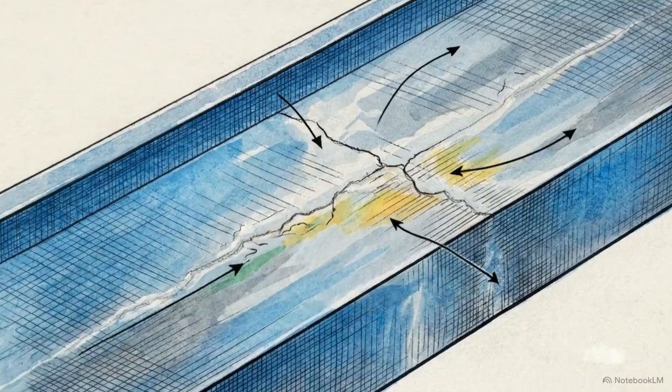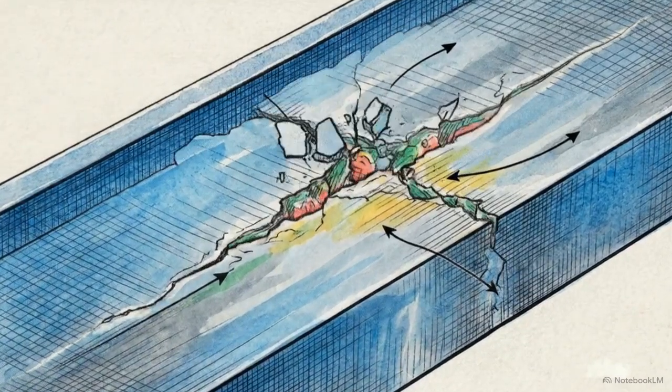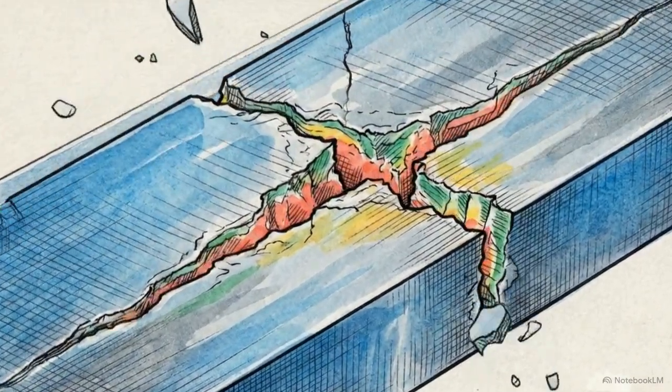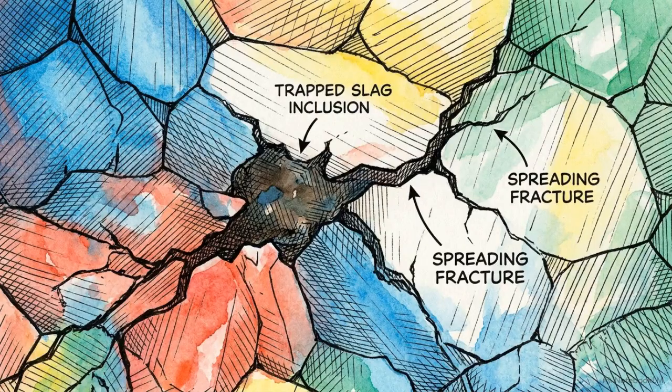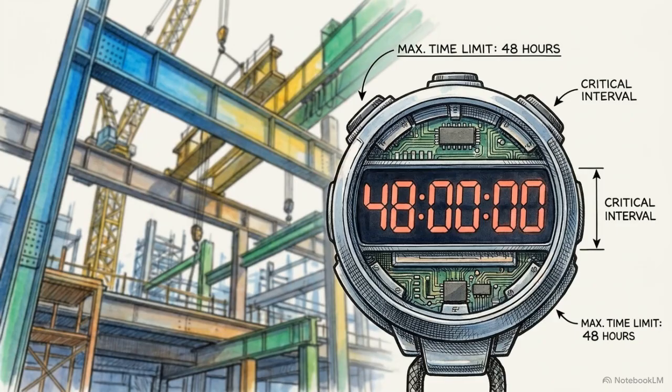This delay targets the high risk of delayed hydrogen embrittlement cracking, which can tear through high-strength alloys long after the arc is extinguished. When this delayed cracking occurs, it actively seeks out existing micro-inclusions or trapped slag as its initiation site. With advanced metallurgy, time itself becomes a critical inspection parameter that must be rigorously tracked.